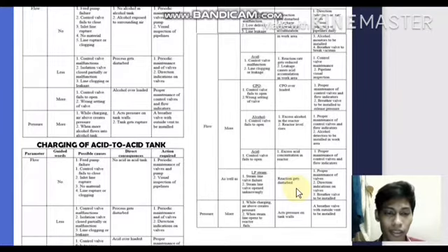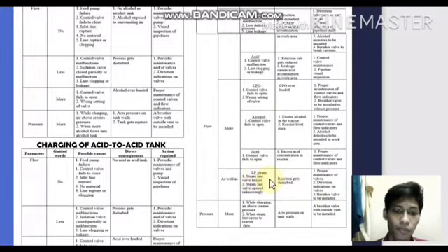So that means the production will be disturbed. And then to avoid this possible cause, we need to maintain the valve, install direction indication on the valve, and install the breather valve for the steam line.